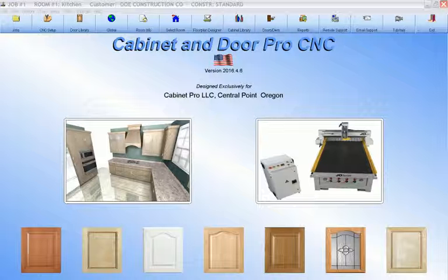On any cabinet that is designed within Cabinet Pro, not only is the bid automatically completed, but the CNC machining has already been calculated and completed as well. The holes for adjustable shelves, dados for vertical partitions, horizontal partitions, and fixed shelves, as well as the drawer guide holes for either side-mounted or rear-mounted drawer guides, and other machining is ready to be machined on the CNC router.